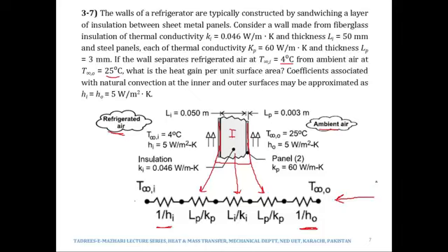So how would you be able to find out the heat transfer? See, we will be writing Q as delta T over resistance, and what temperatures are we given? We are only given this temperature and this temperature. So we have no choice but to write this temperature difference into the numerator. So what will we then write into the denominator?